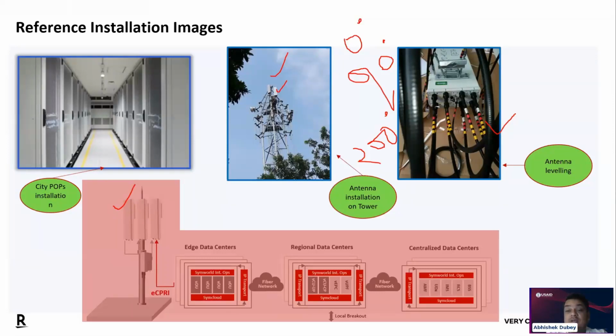So nowadays it's not only single band antennas. We are using multi-band in most of the configurations, and it is based on the customer's availability for which you're working. If the customer is having 2 carriers, then you have to purchase a dual band antenna. If the customer is having 3 bands, 3 carriers, then you have to purchase tri-band antennas, where you will have 3 bands in the same antenna. So you need not install multiple antennas for multiple frequencies. There will be one antenna in one sector for all 3 frequencies.